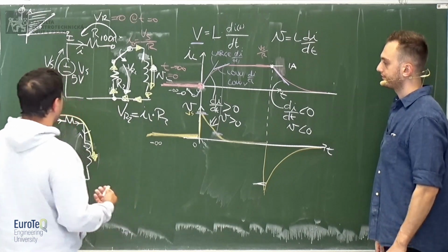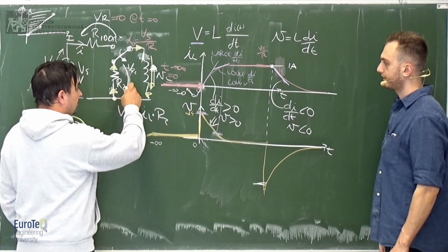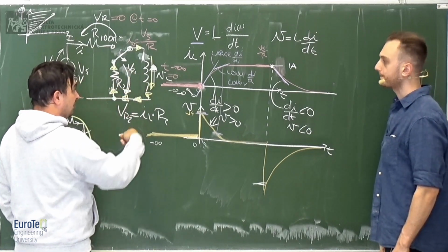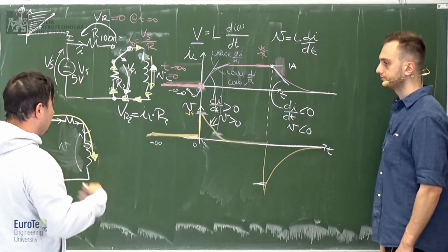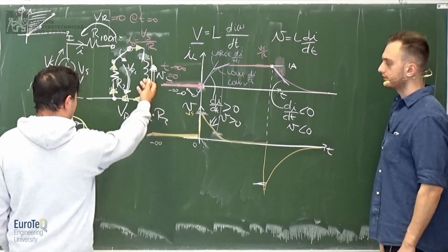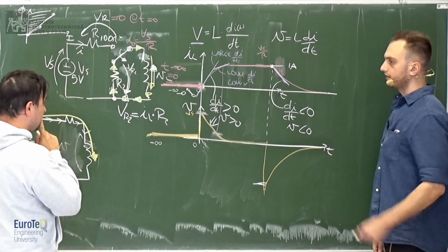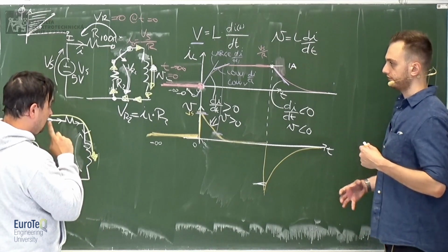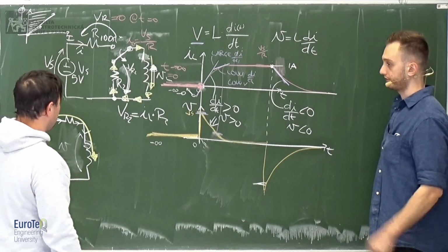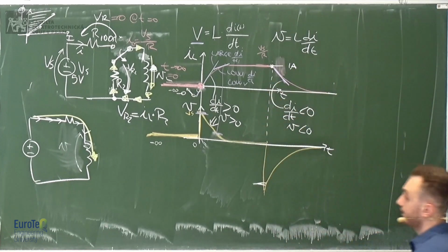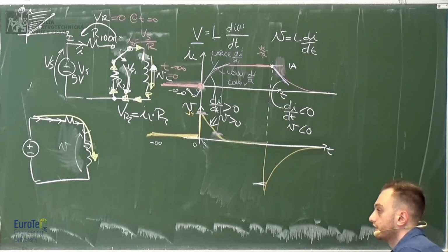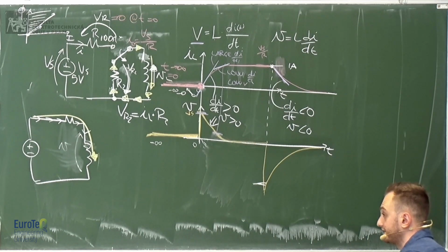And if you close it with the short circuit, it will run forever because there is no transfer of energy. It needs a resistor to dissipate this energy. Otherwise, there is no net transfer of energy from the inductor to the resistor. That's why some diodes have a resistor to limit the impact of the current going through the diode, because you'll have a flyback diode on inductors. Yes, so there's sometimes a current limiting resistor there in case there's a lot of energy, and if you're switching that inductor really fast.